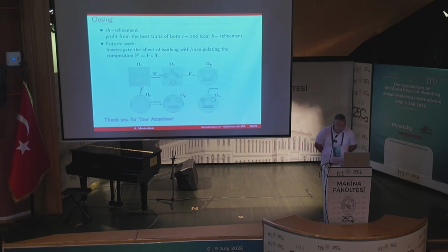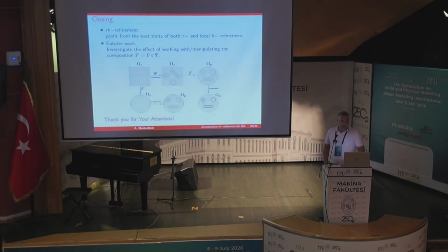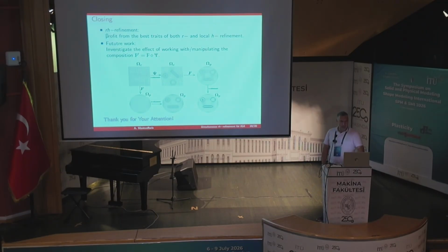Okay, so to draw some conclusions, we tested this technology of RH refinement by combining node relocation and local refinement in order to get the best traits of both worlds. I would say the best trait of local H refinement is that you can locally refine the mesh at will where you want it. But the extra trait that is very interesting in relocation refinement is that you can align and you can reparameterize so that you capture much better features of your solution.